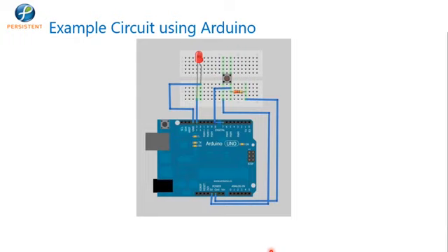And with the control of that position of the push button, press and release, we want to control the actuation of the output LED. So as already highlighted here in the diagram, the LED we will connect to some pin number, maybe your default inbuilt LED pin 13, and then have the connection of your push button to the ground. Let us see the connection of the circuit here.